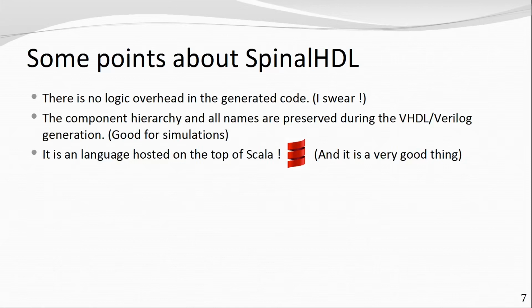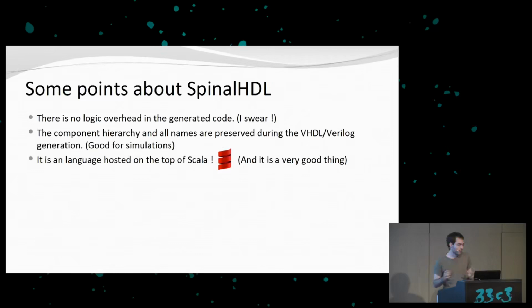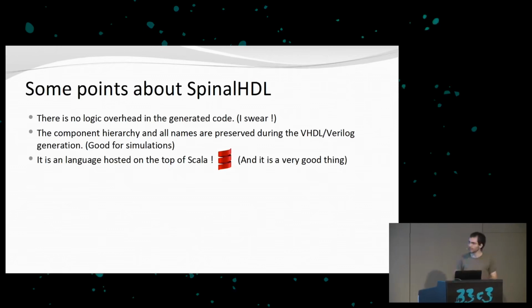You know, for example, there is Vivado HLS where you can write some, not arbitrary, but some C algorithms that will be translated automatically into RTL. So SpinalHDL is not that. SpinalHDL is really an RTL approach where you will have to define registers a little bit as before and gates a little bit as before.